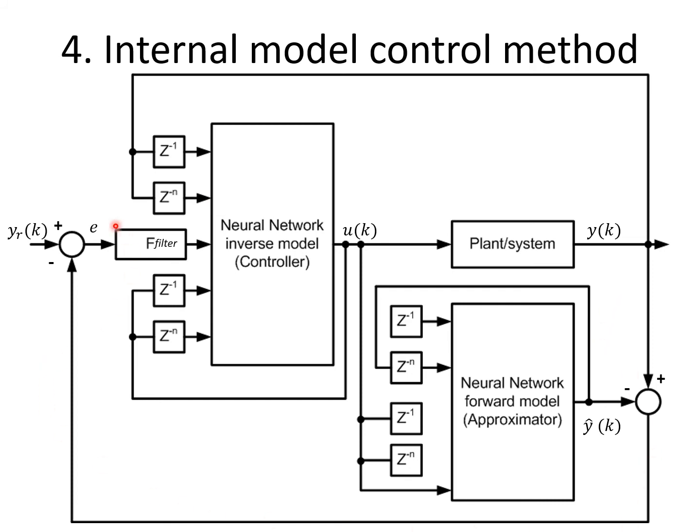So you can see in these strategies, you have to use the model as a controller itself. And we do not have to exactly follow the normal four elements. So of course, the neural network model control goes to the plant. Actually, we also have a valve, the final control element. Okay, and also definitely we have measurements. But the measurements are for both U and Y. So it's not like the standard measurement of Y only. You also measure the Y's, and we can also measure the U's. We need to measure the U's as well.